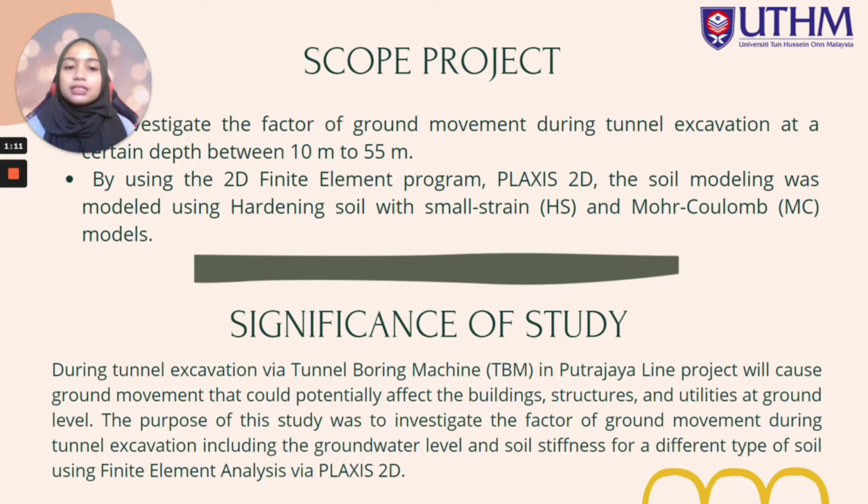For the significance of the study, tunnel excavation using TBM in Putrajaya Line will cause ground movement that could potentially affect the building structures and utilities at the ground level. So the purpose of this study was to investigate the factors of ground movement during tunnel excavation, including the groundwater level and the soil stiffness for the different types of soil using PLAXIS 2D.